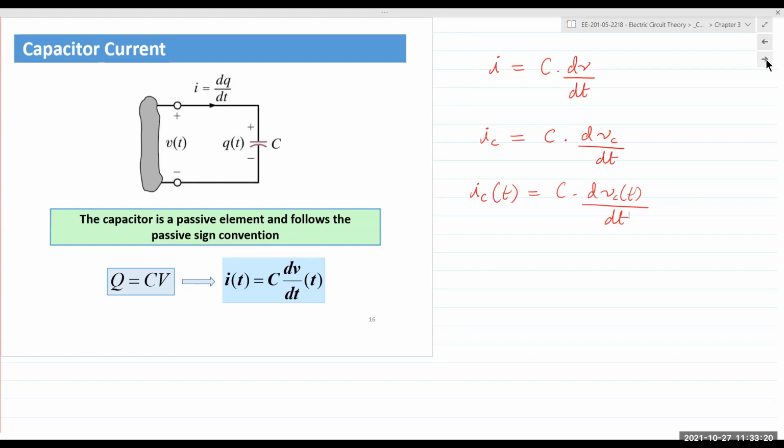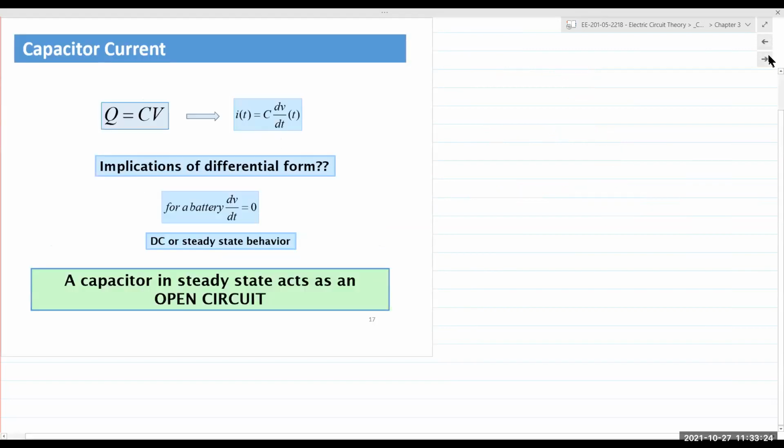Now, the voltage we'll take a look at later. One more thing about that, a mathematical explanation for the explanation that I gave before. Mathematical evidence: I of t is C dV over dt, the rate of change of voltage. If voltage is constant, not changing, then the rate of change of voltage is 0. So I is 0, right?